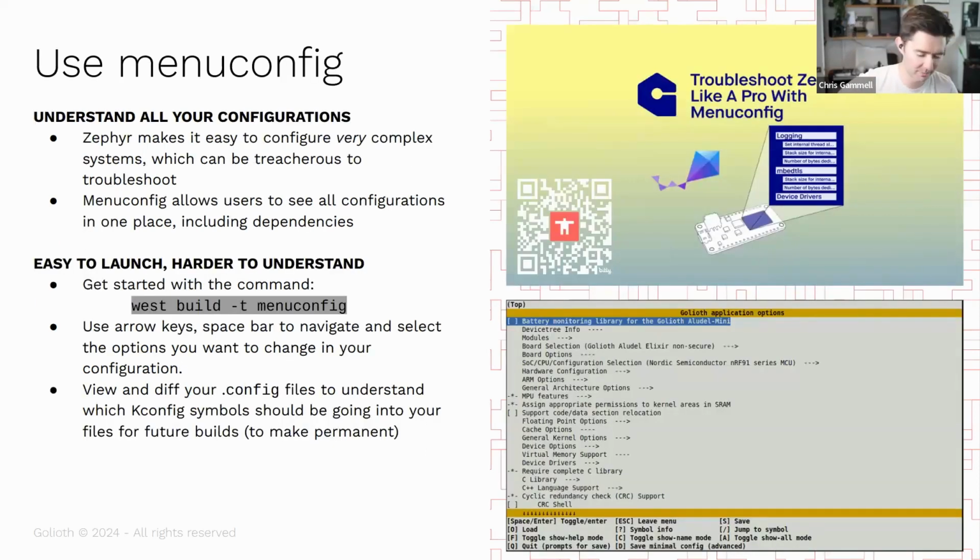This is, again, I mentioned at the beginning, starting with beginners. People who are in the Linux world, they're like, oh yeah, menuconfig. Of course I know menuconfig. Me as a hardware engineer, I was like, what now? And so this was a huge one for me. Yes, you're building up all this stuff with the device tree, and you're starting to dig down through the structure that you're setting up in these files, but I didn't know. It took me a while to figure out that yes, you can go into menuconfig and see it all in one place and try and change it and modify it, and then you can click on one thing and nothing changes because there are dependencies baked in there too.